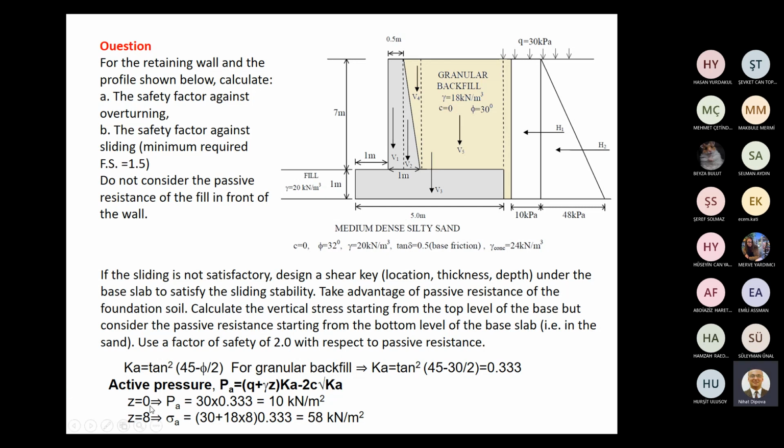So PA at depth 0 is equal to 10 kilopascal. That's resulting from this surcharge. And when we go to the bottom of the wall, it will be equal to 58. 48 comes from PA, and this 10 kilopascal comes from surcharge.